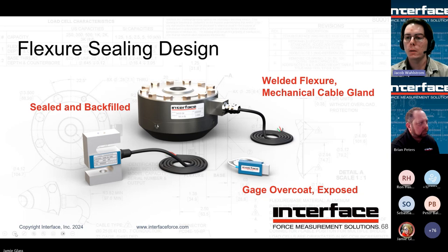And it really depends on the application, right? So we have some load cells that are being used in oil drilling applications with 20,000 psi of oil around them. And then on the other side, we have load cells that are being used in high vacuum environments where everything needs to be vented and outgassing is a concern. So really working with the applications engineer on your unique environment and use case is really important in getting a load cell that's going to be good for you.